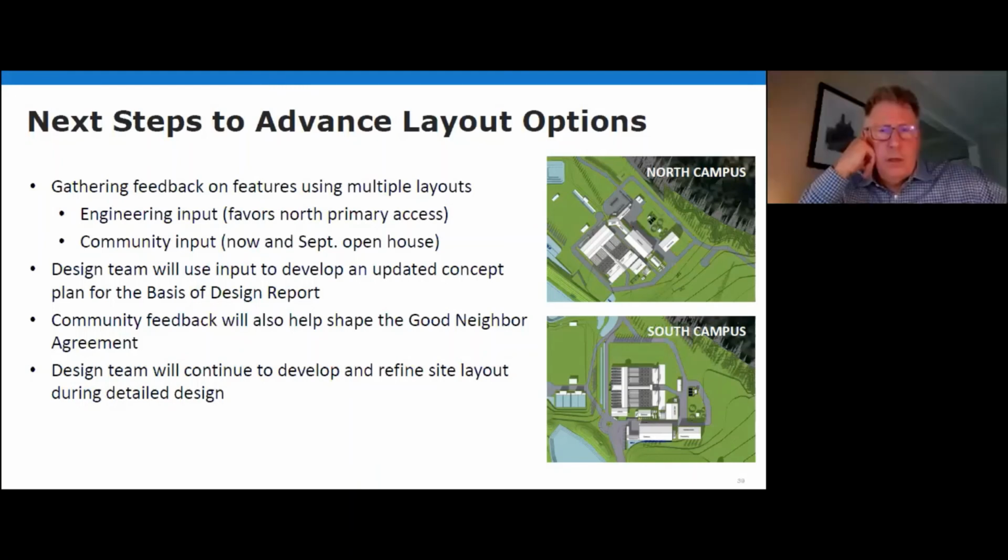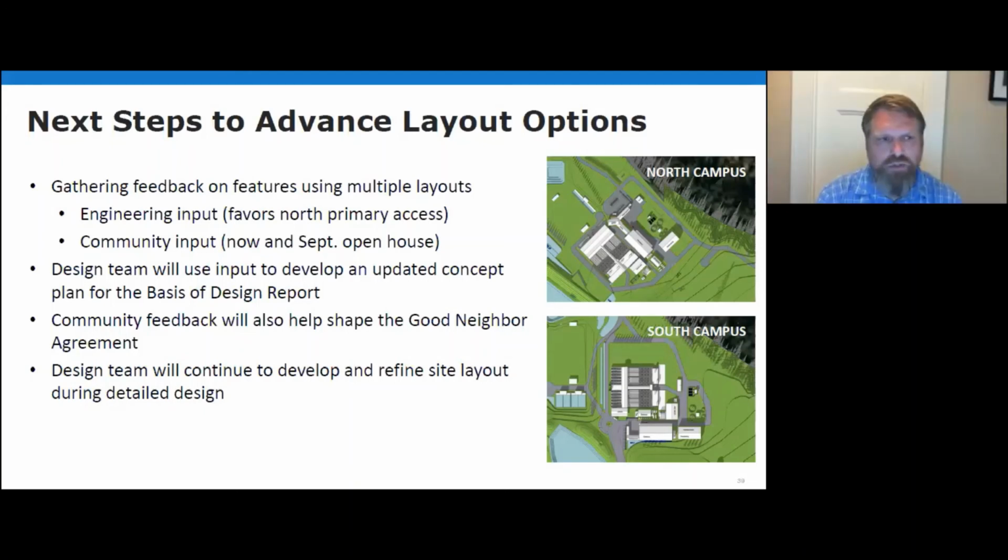Can we have our landscape architect respond to that? That's going to be a better person to answer. Absolutely. We didn't really discuss the whole stormwater strategy for the site, but we are looking at trying to design conveyance swales alongside most of the roads to capture stormwater right next to paved areas and treat it as close to the source as possible.